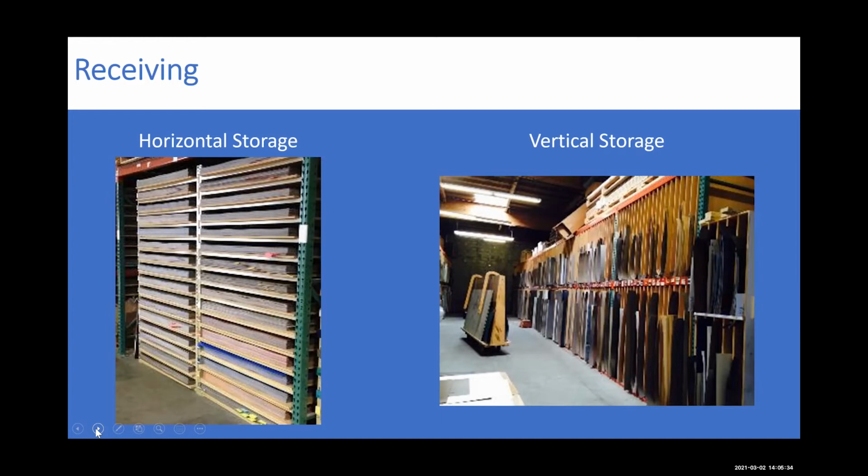Distributors provide more than HPL to the trade, which means that they have less space to store laminate, and as such, they store laminate in vertical bins. This requires that the laminate be bent for storage. If it's stored bent for a long period of time, it becomes harder for the mill worker to flatten and could lead to delamination from the substrate in a finished piece of millwork.